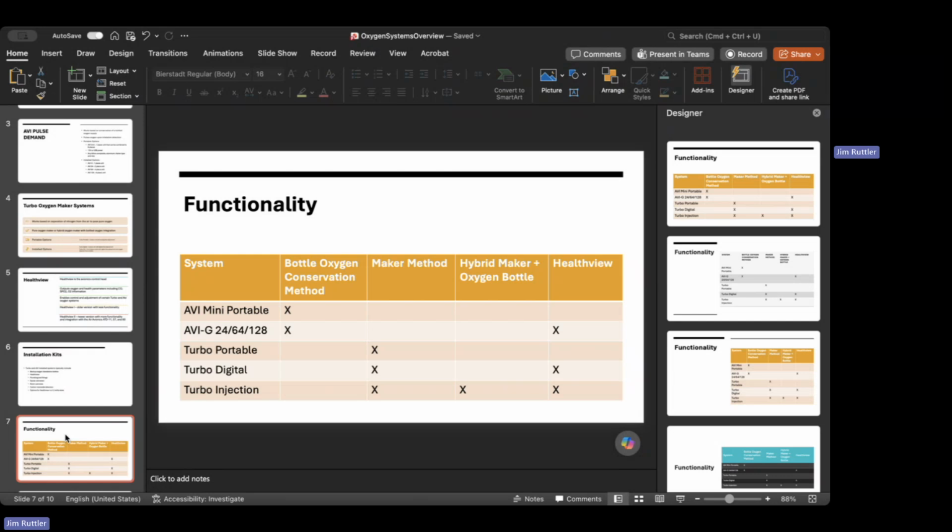It also works with the HealthView, although it's only an output of the turbo information, including flow rate, onboard temperature, and humidity. There's no control because there's nothing to control. It automatically knows the altitude on board the digital, and it outputs the appropriate flow rate for the altitude. In fact, it just pegs the output at a common 1.1 liters a minute at all altitudes up to 18,000 feet.